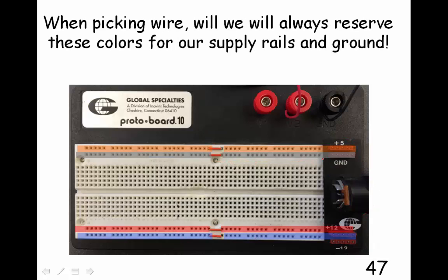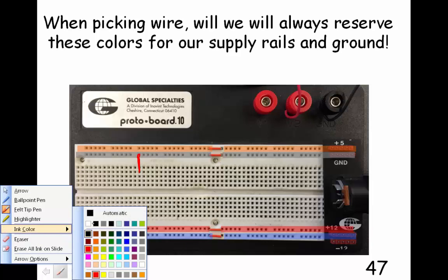When picking wires, just to keep things clear, and it's much easier for us to know what we're doing. I did these circuits for a year. I did this for a living, breadboarding different circuits, and this is the technique that I always used. Whenever I was connecting a wire to a ground, I always used black. Let me show you what that would look like.